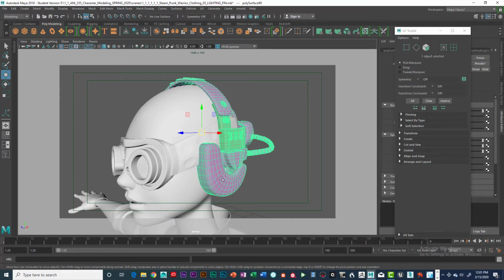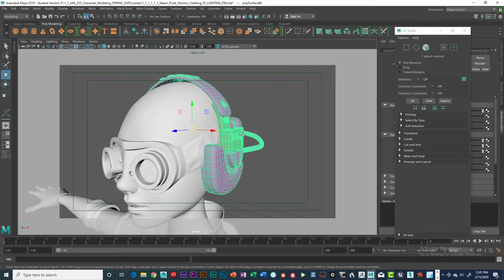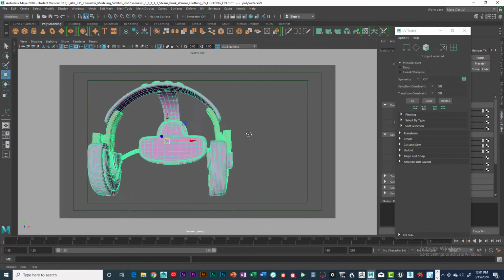Okay, so the next thing we're going to do is, not everything's separated out. I need to add a UV texture to this, a UV map. Right now it's just a jumbled mess because I've been extruding and extracting and separating and all that stuff. So it's really important that we look at this by itself. What I would do is a Control-1 just to isolate this.